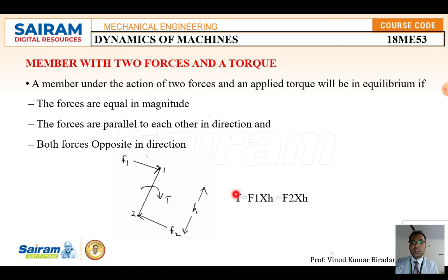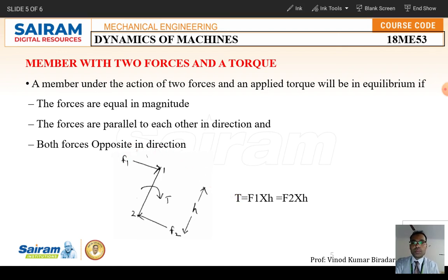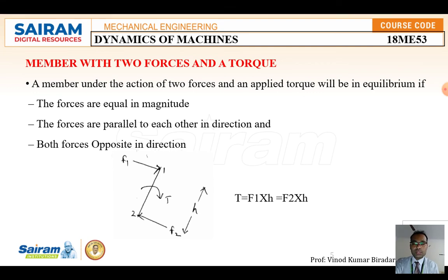You have to write in the examination, with a diagram, these three conditions. When we say the 2-force member with torque is in static equilibrium, the forces should be equal in magnitude. If F1 is 10 Newton, then F2 should also be 10 Newton.